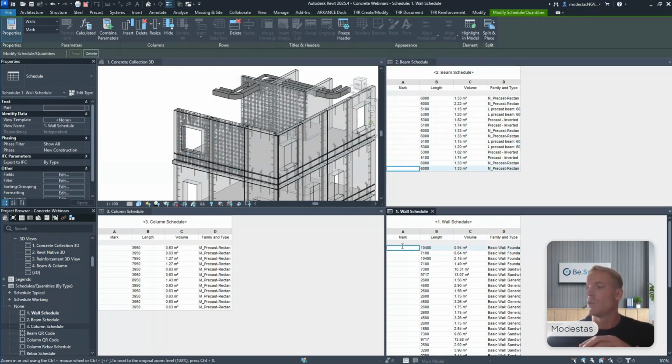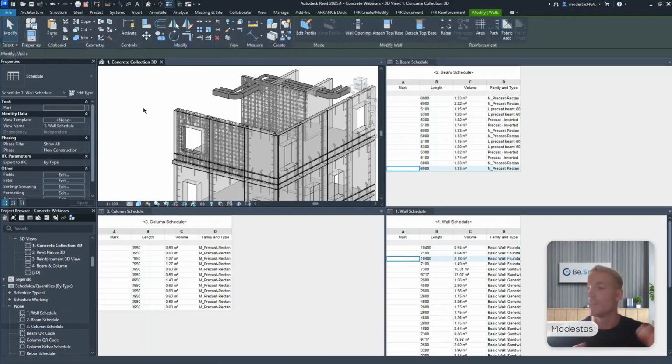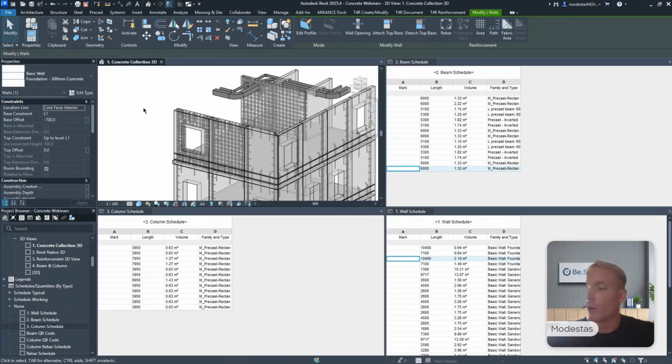And if you would be using Revit itself, right? So you would manually go ahead and type in the mark values that you want to see. And if there are some additional elements that appear later on in the project, you need to go ahead and double check if all the values are up to date, if all the elements are properly set up, right? Which can lead to a potential human error or some misalignments with the documentation that you want to have.